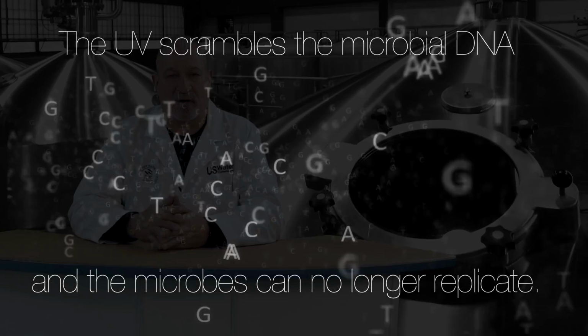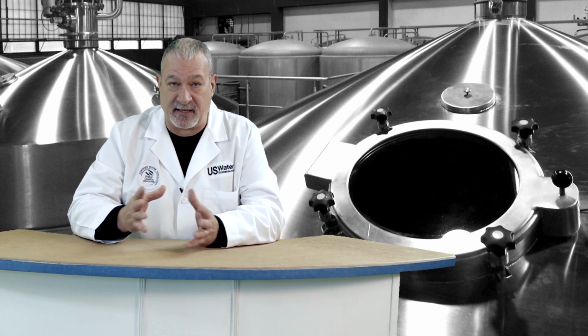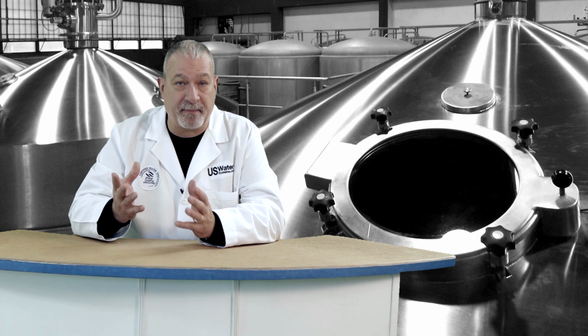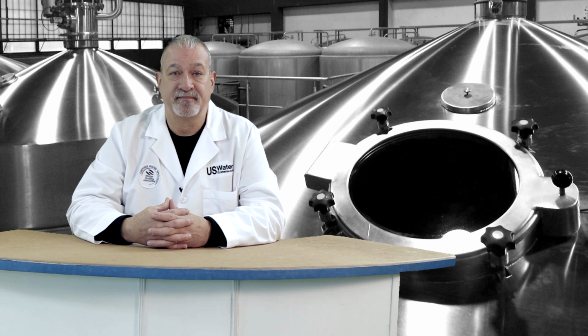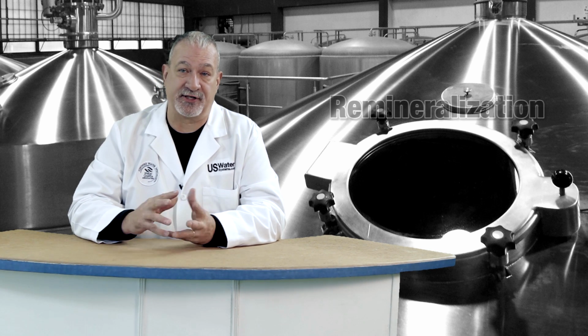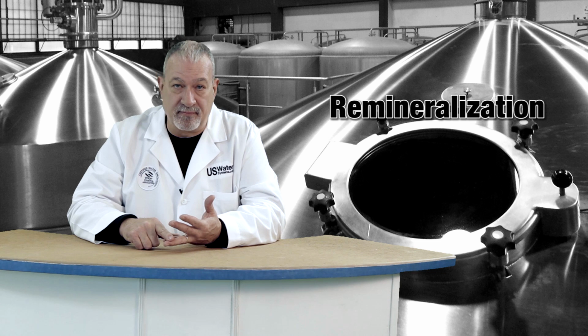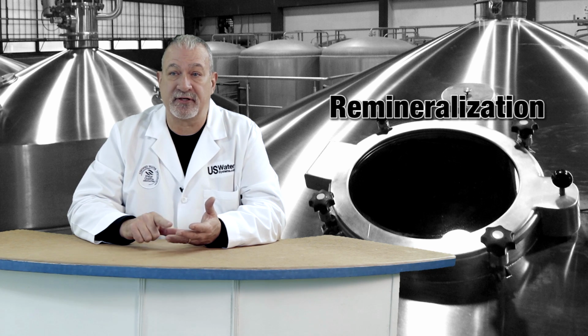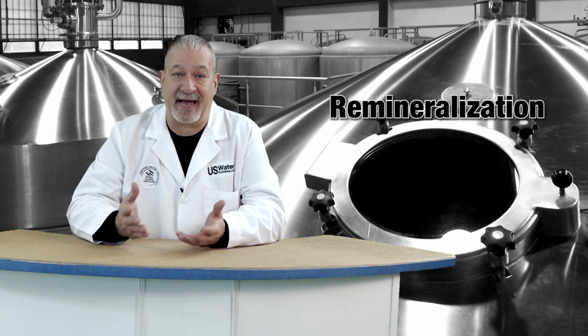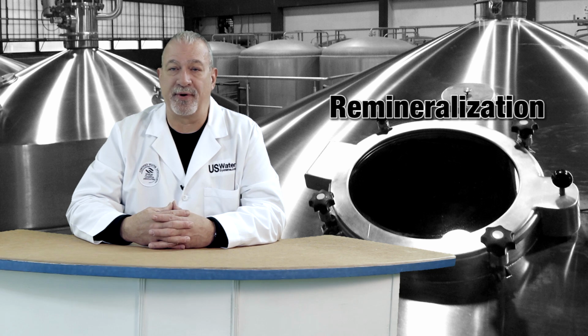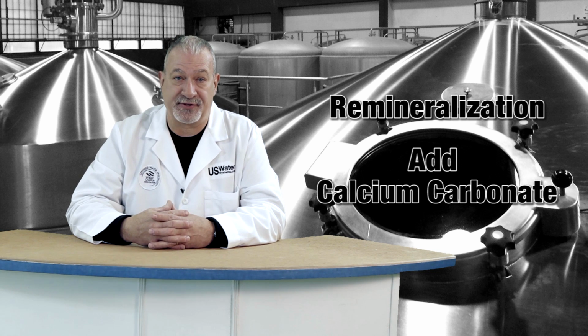Some people are going to ask the question, well, isn't reverse osmosis water low in minerals? Yes, it is. It is low in minerals because it removes practically everything in the water. You're dealing with pure H2O at that point. Now, some people, when they're distilling grain or brewing beer, may want some level of total dissolved solids back in the water. And so at that point we have remineralization.